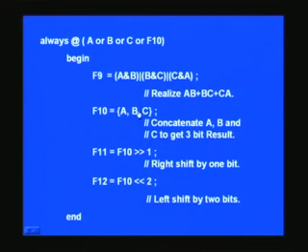Suppose that in addition to this you want to add 3 zeros at the LSB. All you have to do is put a comma here and then say 3'b000, or any other data you want. If you put 111, then 111 will be concatenated towards the LSB side. And so you can insert anywhere, or instead you can put any other signals which are already available here.